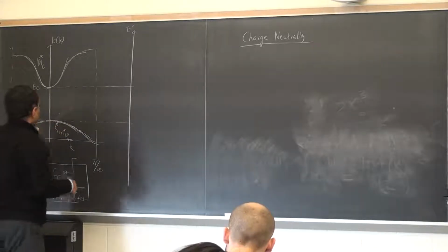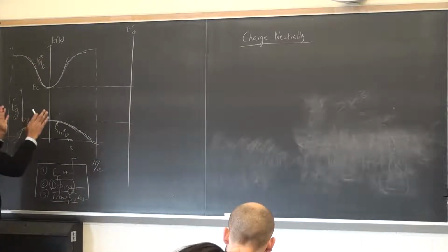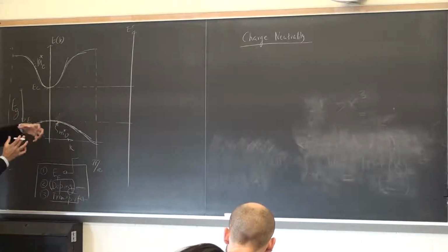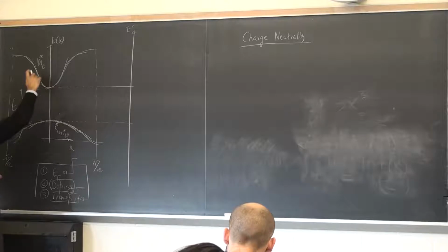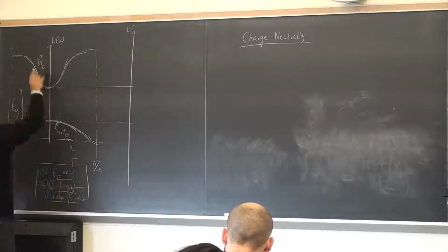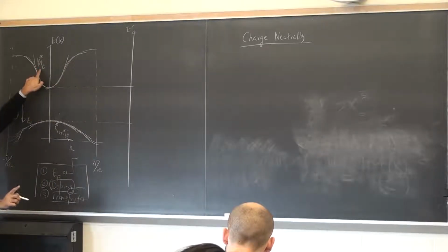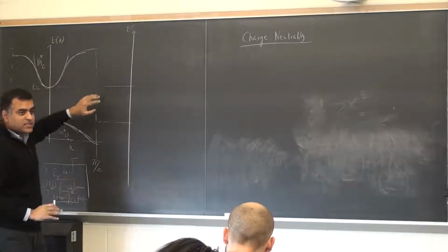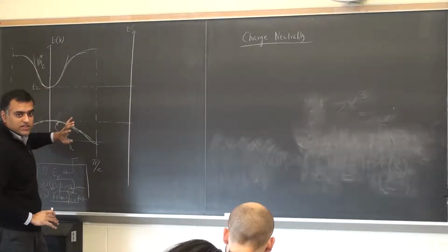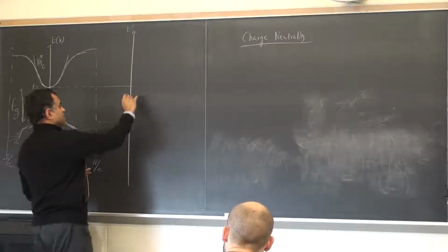But if I have a three-dimensional semiconductor, a 3D crystal, then the electrons are free to move in 3 dimensions, and you have a parabolic band structure. It starts looking just like a free electron, but with a different mass. So we have already found the density of states for such a situation. What is the 3-dimensional density of states?